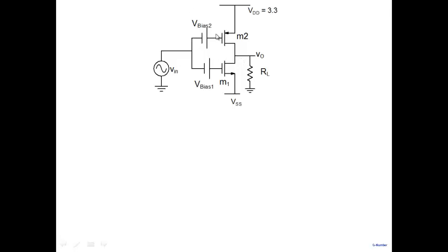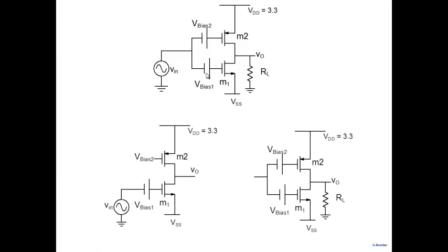Now the issue is we have to realize V bias 1 and V bias 2. Remember, the signal for this amplifier will come from a previous stage, which is nothing but a gain stage here, a common source amplifier of this kind. We are going to design it such that the normal biasing point here is V0 equals 0. That's what we've been talking about. This is 0, and this will drive my class AB amplifier here, so I have to connect it here.